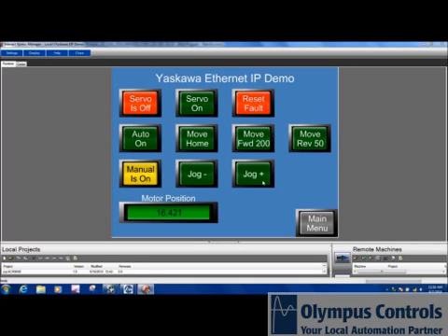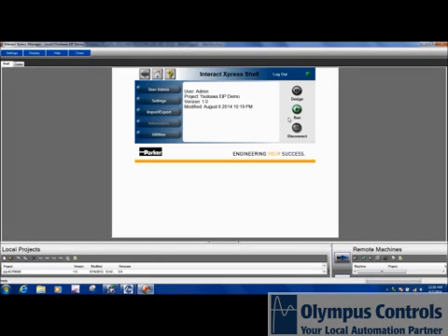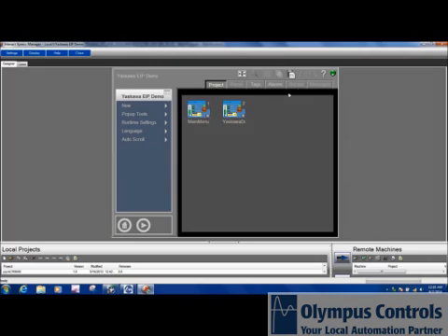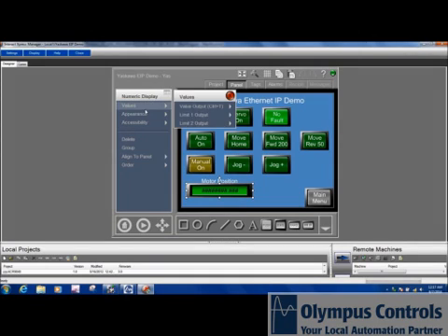We have the Parker IntractXpress HMI screen here, where we already demonstrated that we could reset drive faults, enable the drive, jog the drive forward and reverse, send the drive to a specific position. If we go out of the runtime mode and go into development mode, we'll see that the HMI is made up of several buttons, numeric displays, and whatnot. Those numeric displays are tied to tags